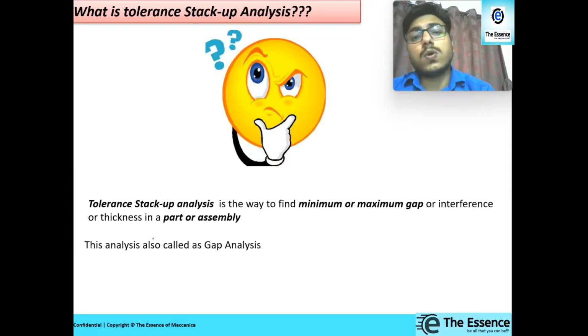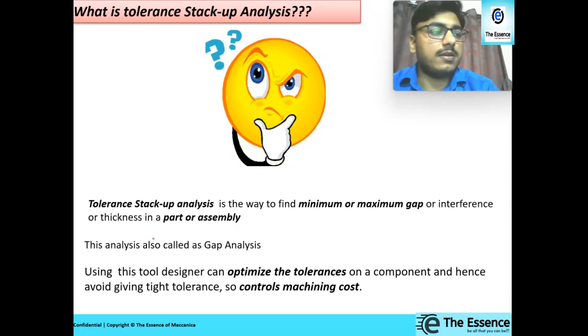This is also called a gap analysis. This tolerance stack-up analysis is also called a gap analysis. Generally, we evaluate the minimum and maximum gap and we figure out whether it is going to work for us or not. So that is what gap analysis is.